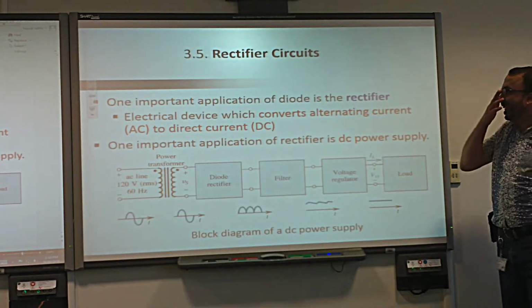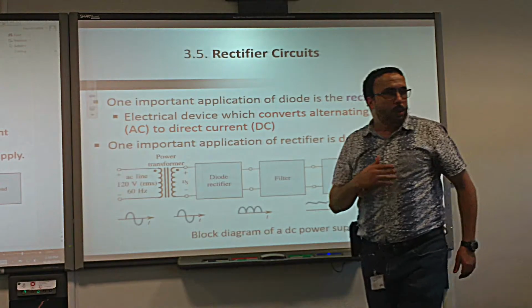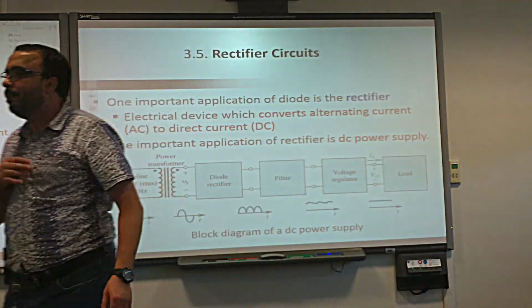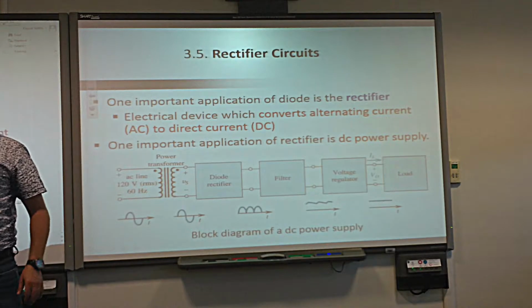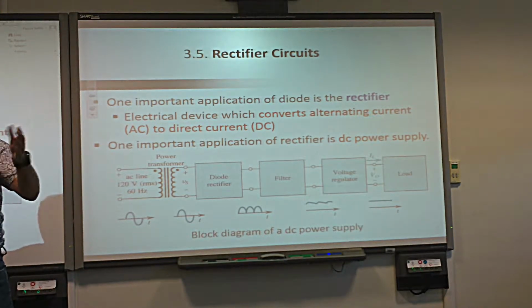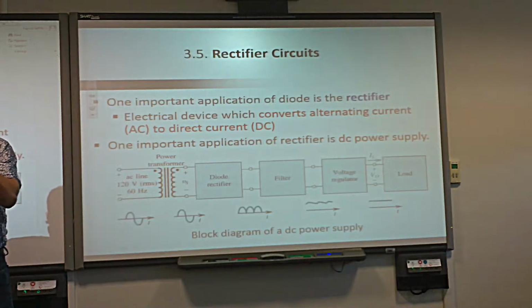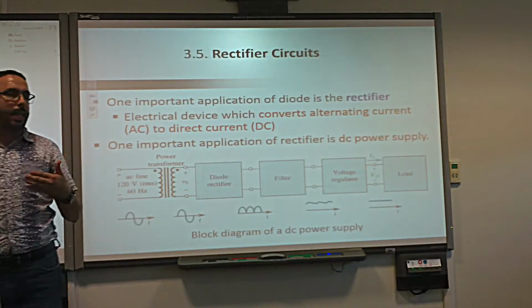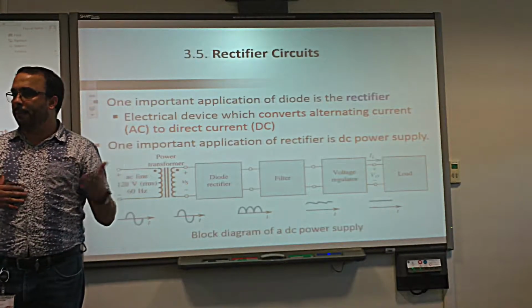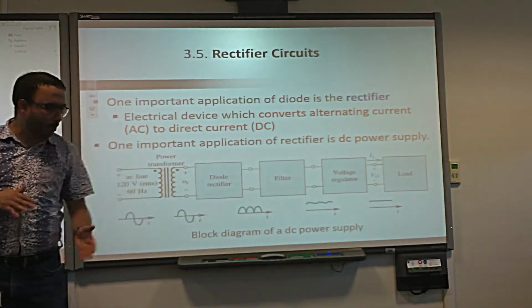Now today, inshallah, we get back to the rectifiers. What do we do with the rectifiers? What do they do? Convert AC to DC. Not exactly. We use them in the conversion, they are just part of it. They make the current move only in one direction. It rectifies the direction of the current instead of going back and forth. Only one way. Means that the output will have only one sign, either positive or negative. Usually we take the positive. So the AC that has plus and minus, after the rectifier will have only plus. And that's the purpose of that.